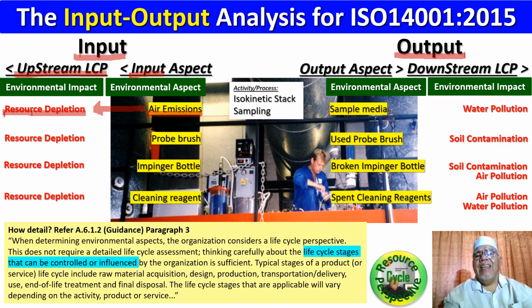These air emissions are being sampled in a thimble, filter, and a few other methods, like impinger, glass flask, you name it. So we call it sample media. Various types of chemicals use different media, and the dust particles are trapped at the filter media.